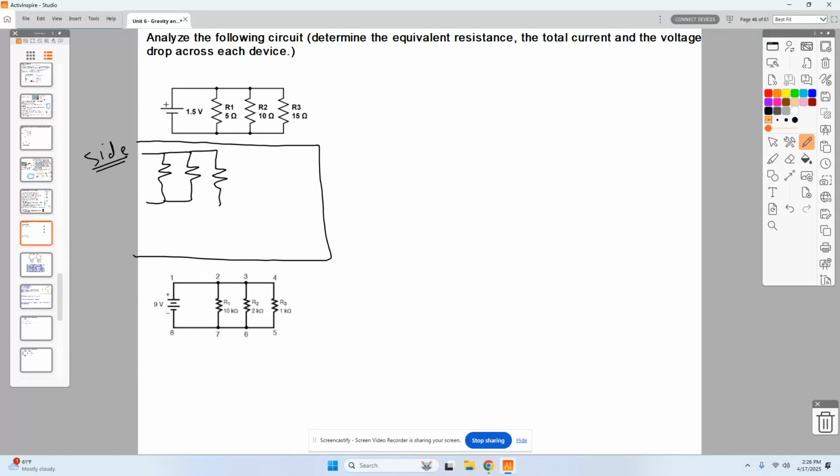Let's say that I have 4 resistors, all of the same value. Let's say that they're all 40 ohms. So every one is the same, all connected together. Would you agree that each time I add another resistor there, I effectively reduce the equivalent resistance because I'm adding more area? If I have 4 identical resistors all connected together, that would be equivalent to a 10 ohm resistor. And how do I know that?